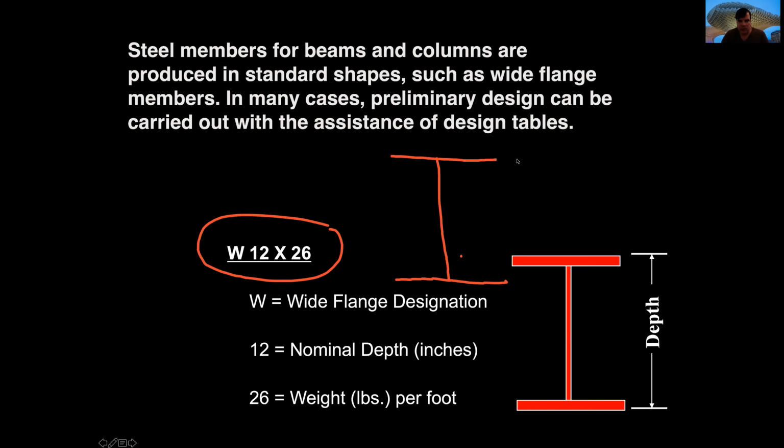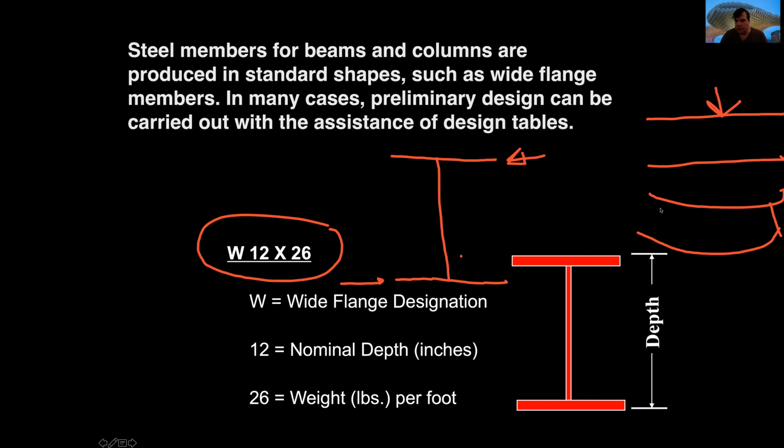We have a lot of material in the top part and in the bottom part, because as you know, when we have a beam and we put a weight in the top part, this beam will tend to deform in this way, and we have compression in the top areas and tension in the bottom areas. I mean, the fibers here will extend and the fibers here will compress. In the middle, we have a section where nothing happens. That is the reason why it's convenient to use this kind of material.